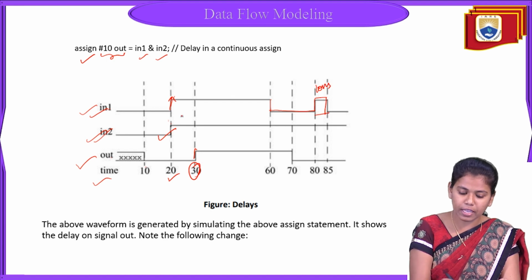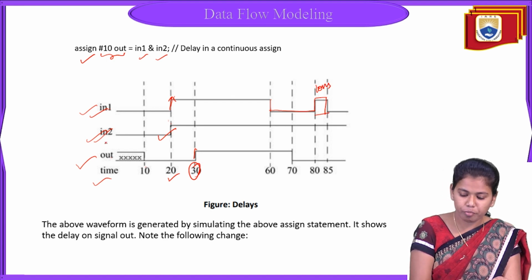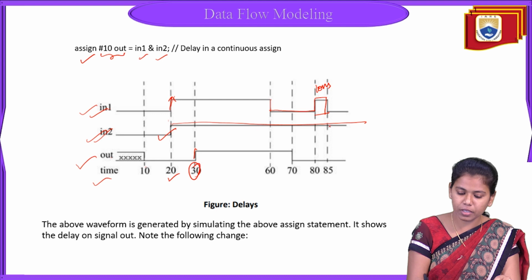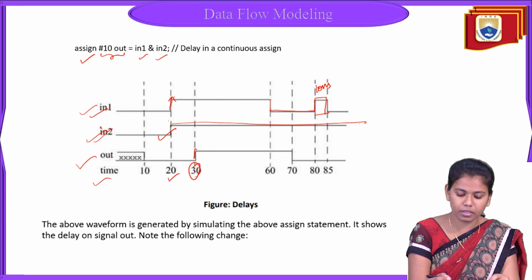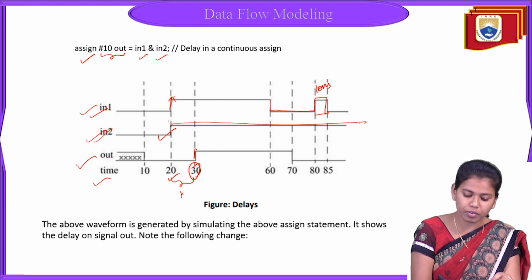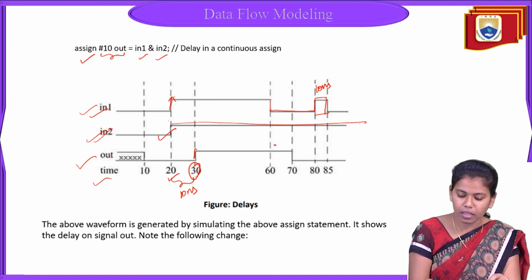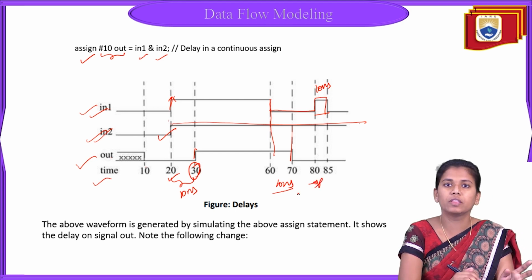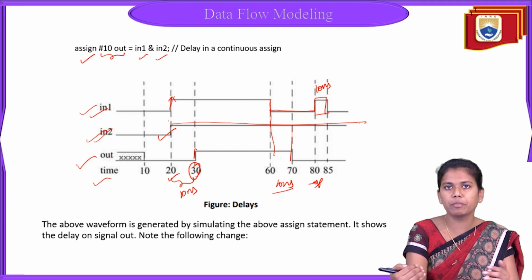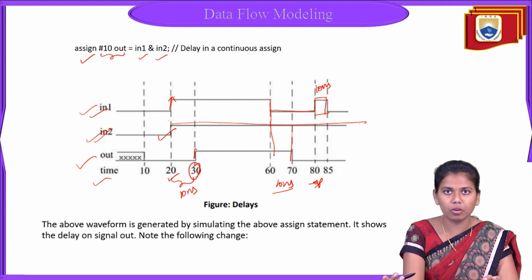Here, with 10 nanoseconds of delay, my input value is going out, whereas for input 2 the output is constant. But when we concatenate both input and output, we see with 10 nanoseconds of delay that we are observing the output at 10 nanoseconds of delay with both input 1 and input 2. Whatever amount of delay we observe at the input, the same amount of delay can be observed in the output also.